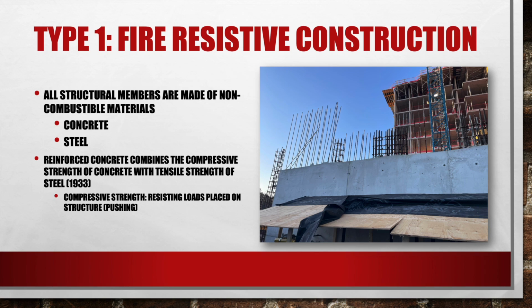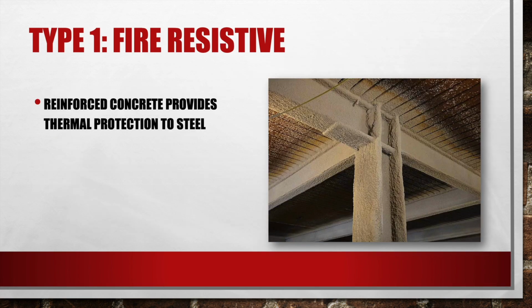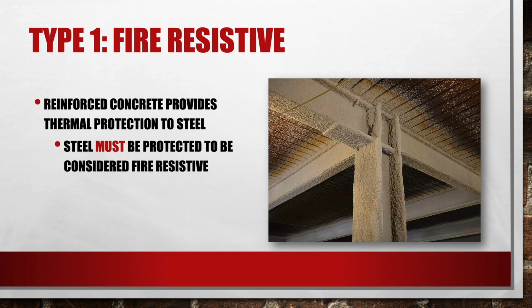So just to review, compressive strength is equal to resisting loads placed on the structure, or essentially pushing forces, where the tensile strength of steel takes up the tensile forces or pulling forces preventing the concrete from cracking. Now, reinforced concrete provides thermal protection to the steel. And it's important to understand that the steel must be protected to be considered fire resistive.